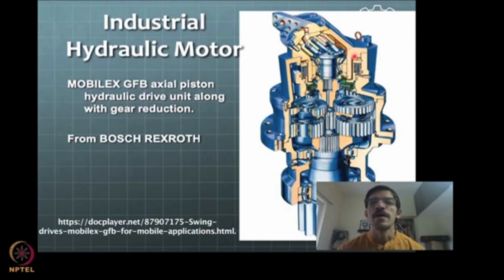Okay, and once that piston is in its end position, then the hydraulic force will be removed here, and then the next piston will be operated. Okay, and then the next piston in this position will be again pushing this to the end position, and again this operation continues with multiple pistons that are there, and that is the way this motor is rotated.